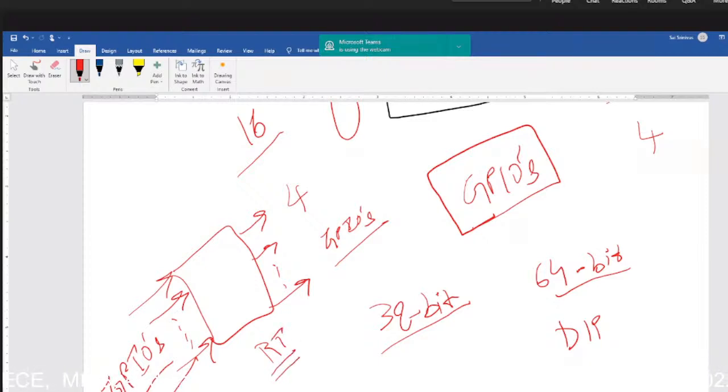In the simulation environment, from the timing waveform diagrams or from file IO operations, you will be able to log the data, compare it with your reference data, and check the functionality. But it is not always the same. If the simulation is valid, it doesn't mean that the circuit sitting on the real FPGA chip will work in real time. There is no guarantee.